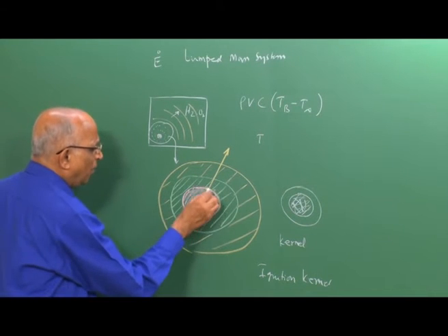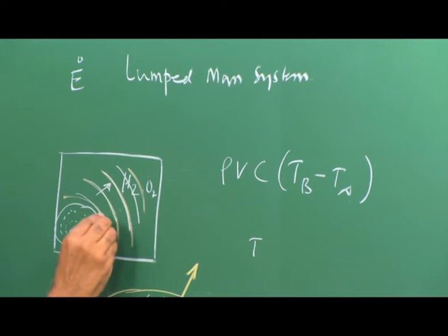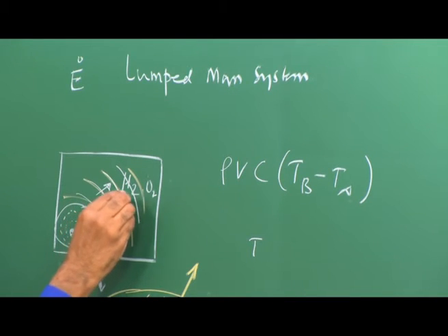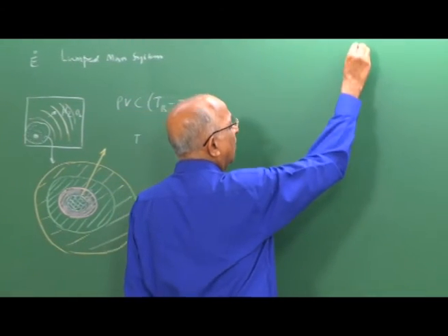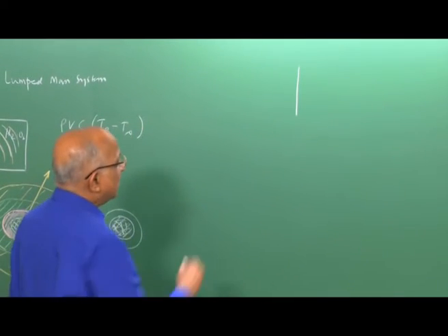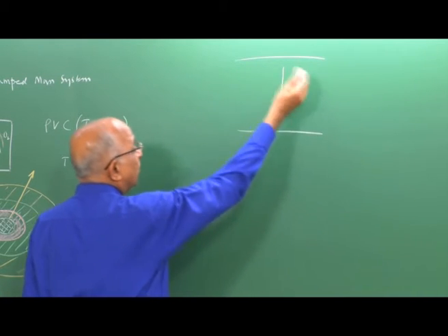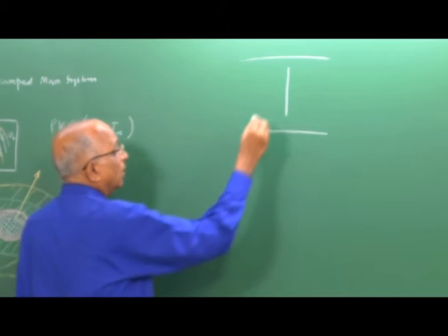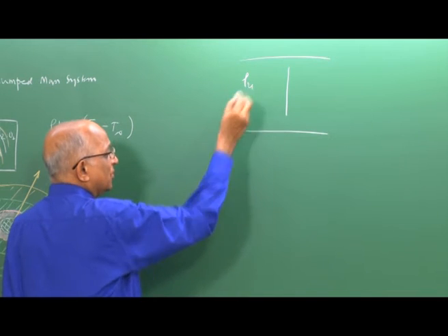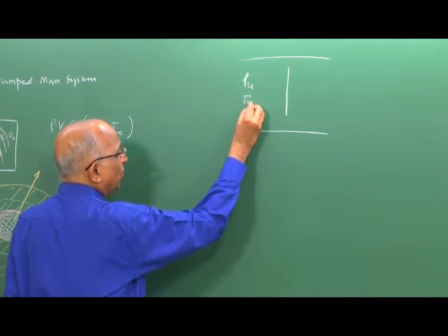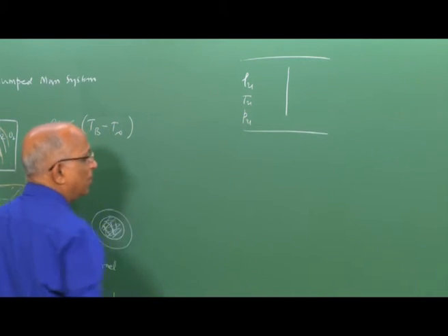Having specified the problem, let us see how to go about it. Let us first ask what is the speed at which the combustion zone propagates out, that means the speed at which the chemical reactions are going forward. Let us forget about curvatures. Let us say I have a zone of combustion in a pipe or some particular medium, in which I have unburned gases. Unburned gases are at density rho u, at a temperature Tu, and the pressure of the unburned gases is Pu.